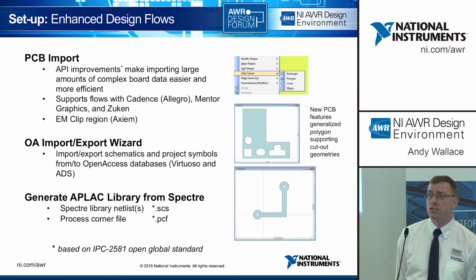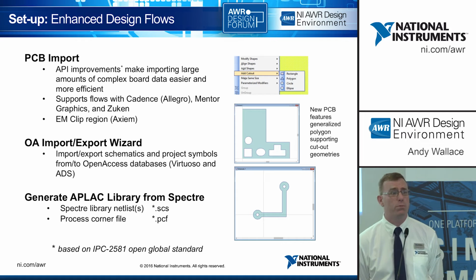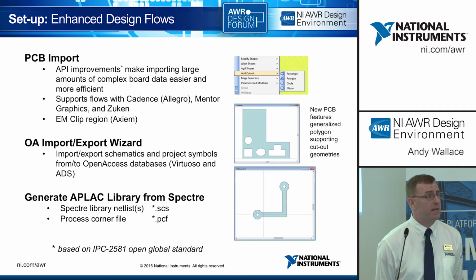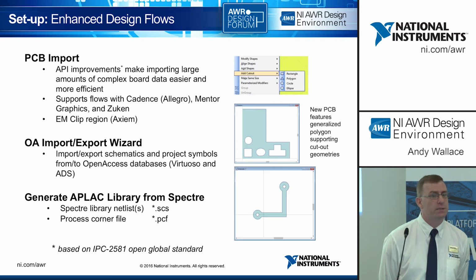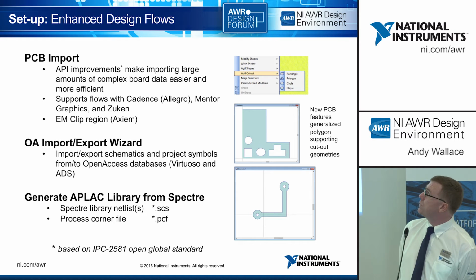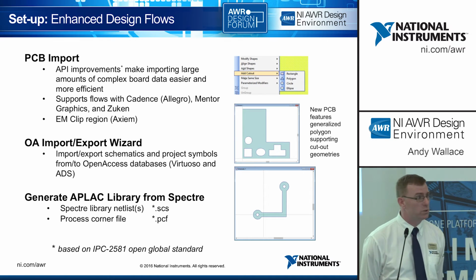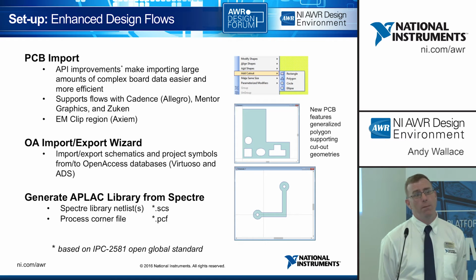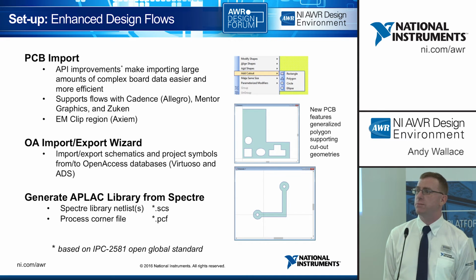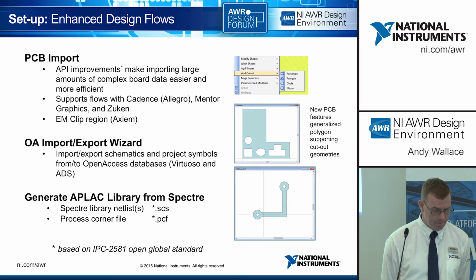We can clip areas that we import and have specific areas around signal traces, for example, or bring in the whole board. And some of the EM simulation improvements for things like clip area take that into account. So we're able to bring complete boards into the design. And of course that flow works with some of the Cadence tool set, things like Allegro, Mentor Graphics and Zuken tools as well. So that should be a one-button push import and off you go, simulating that particular portion of the design in Microwave Office in this case.